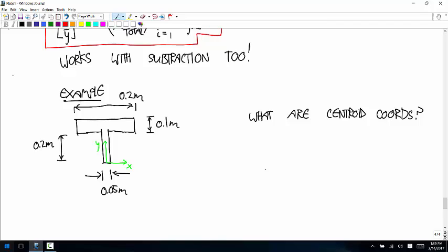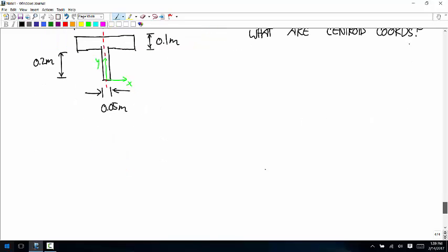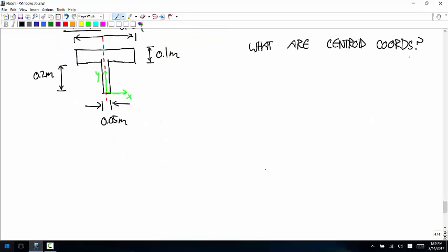Well, you can see that there's this line of symmetry, and that cuts down the amount of work we have to do. What do we know, the vertical location of the centroid or the horizontal location? Yeah, so we know the horizontal location. Now we just have to figure out the height of the centroid.